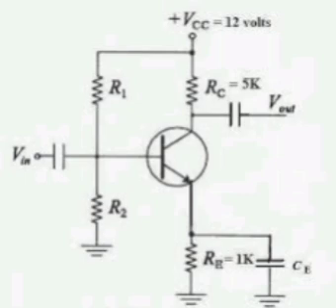The circuit is a 150 volts input in series with 100 kilo ohms, in series with 50 kilo ohms. Across that 50 kilo ohms we connect the voltmeter V. Given sensitivity of voltmeter: SV1 equal to 1000 ohms per volt, SV2 equal to 20,000 ohms per volt. Full scale voltage VFS equal to 50 volts. Let RV1 be the internal resistance of voltmeter. RV1 equal to SV1 into VFS, that equal to 1000 into 50, that equal 50 kilo ohms.